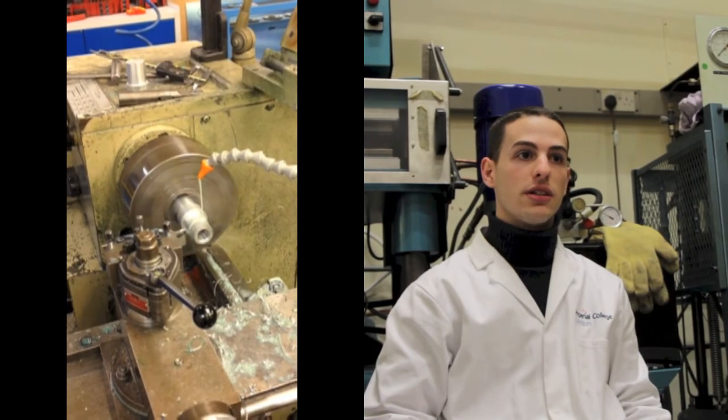The first thing we manufactured was the aluminum hub. We used a lathe and a process called turning to reduce the diameter of the initial cylinder. We then drilled the hole of 16mm through its center. The hexagonal shape and multiple holes of the hub were produced by milling and drilling with the help of a CNC